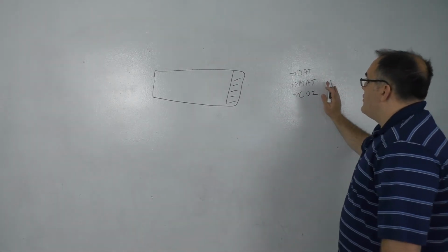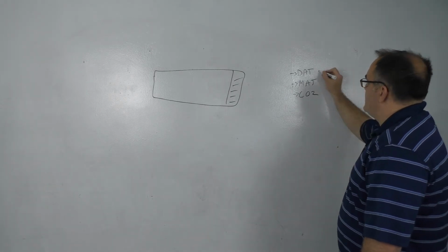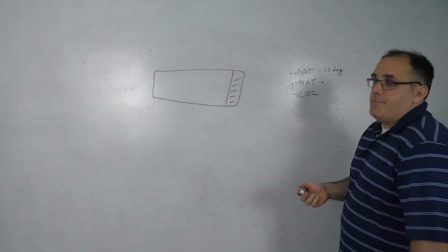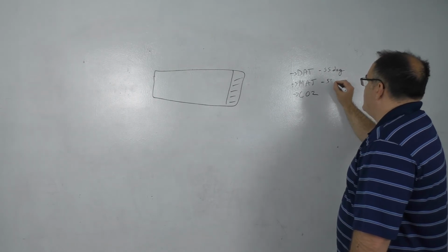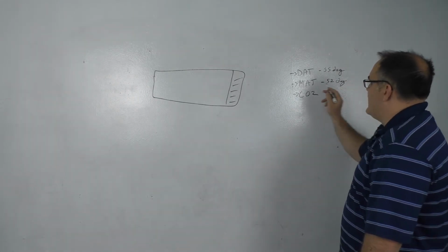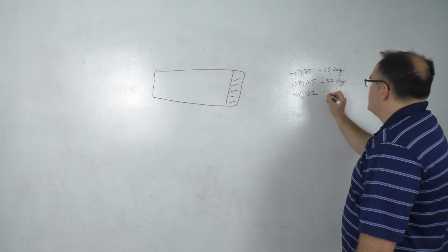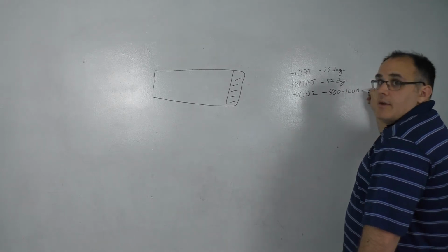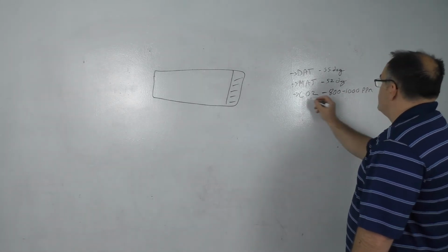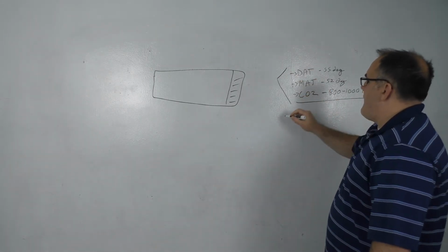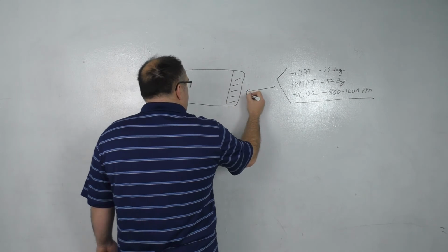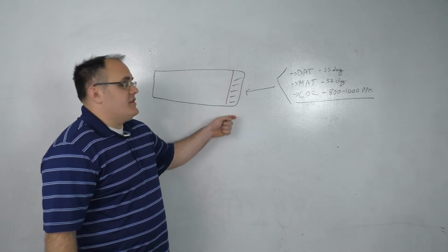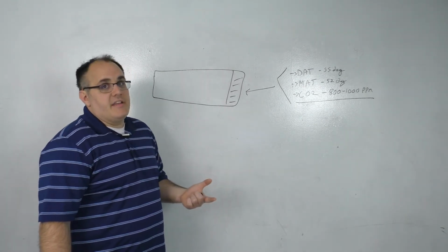Okay, so when we're controlling discharge air temp, basically what we're doing is we're maintaining maybe 55 degrees. And when we're controlling mixed air temp, we may be controlling 52 degrees because we're going to have a little bit of heat gain before we get there. And then CO2, we're controlling to maybe 800 to 1,000 parts per million. So all of these right here will end up controlling the min position. Notice I said min position of the economizer. And these will be using PID loops.